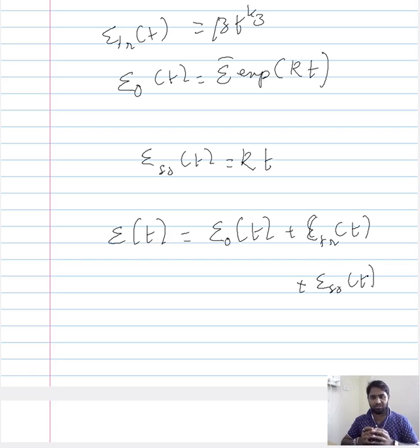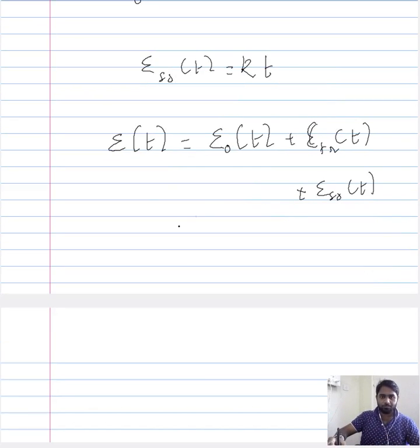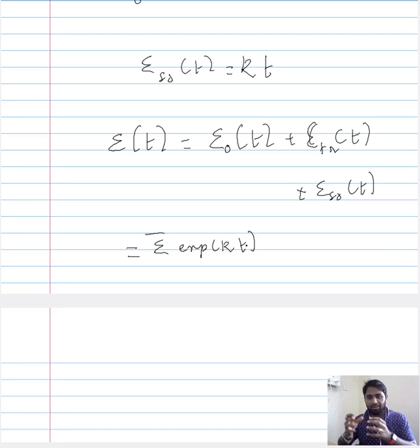So whatever Andrade has done is, he has sectioned the overall creep into two different stages. The first stage is the time independent region, and the second stage is the time development region. In the time independent region, this relates to our instantaneous creep region, and this is how he expressed the strain during the time independent region.